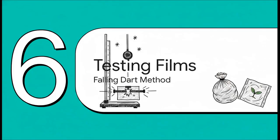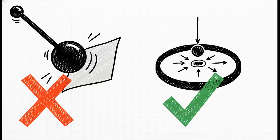Moving on to Section 6, testing films with the falling dart method. Okay, so what happens when pendulum tests just don't work? If you try to swing a heavy pendulum at a thin piece of agricultural film or a garbage bag, it's not going to give you useful data. We have to pivot. The reality is that pendulum tests generally measure the notch sensitivity of a thick, rigid material in a single, perfectly controlled plane.